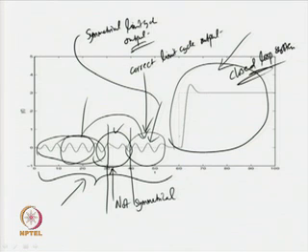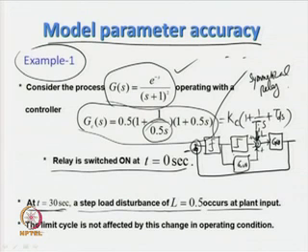This is the dynamics or output you get from the closed loop system. The limit cycle is not affected by this change. Which change? The static load disturbance, or step load disturbance, in normal operating condition. That means, because of the presence of integral action of the PID controller, the ill effects of static load disturbances are eliminated successfully in steady state condition.